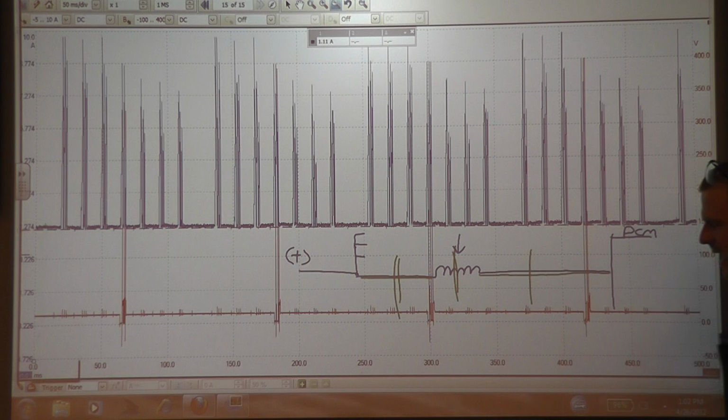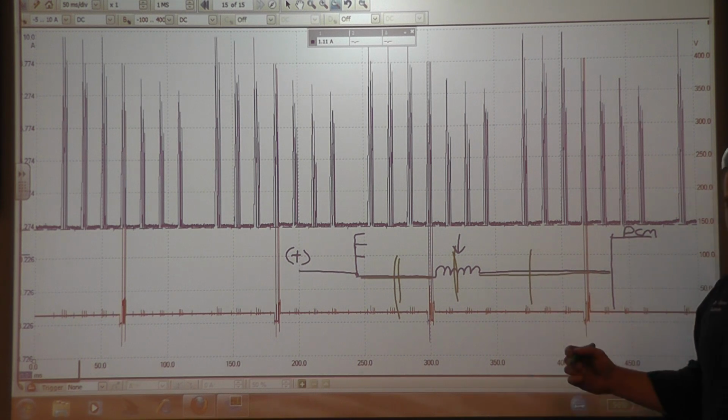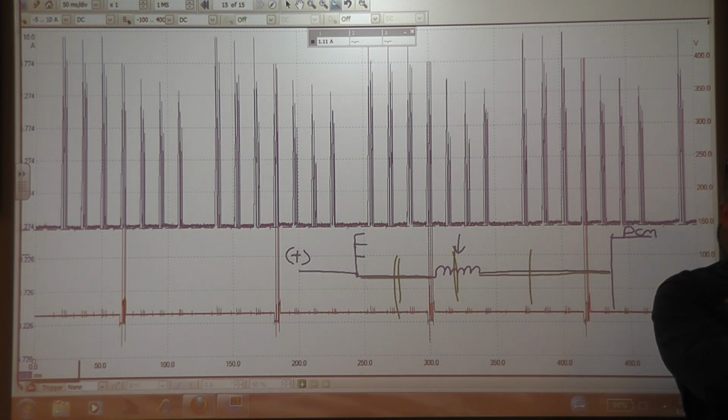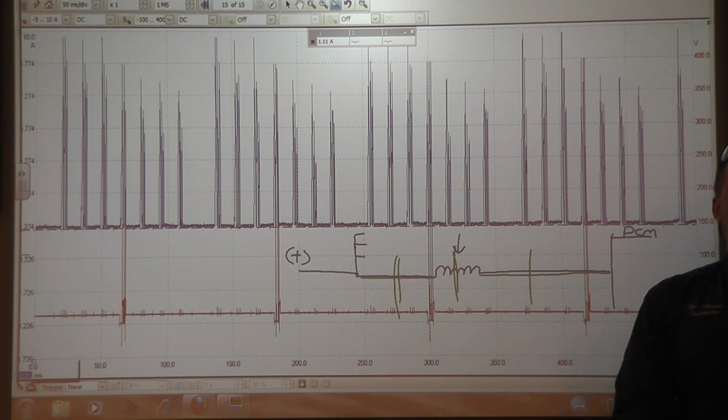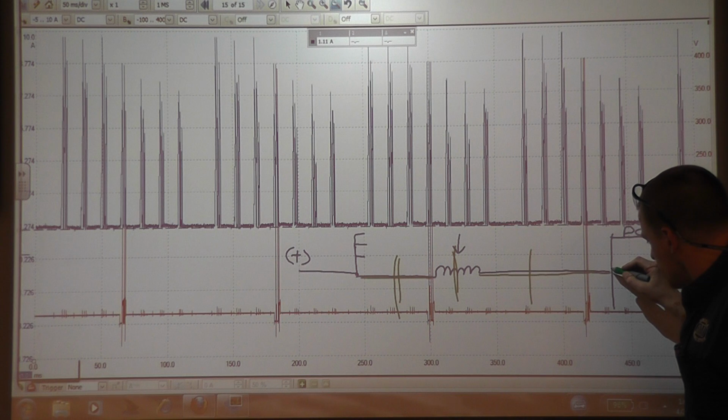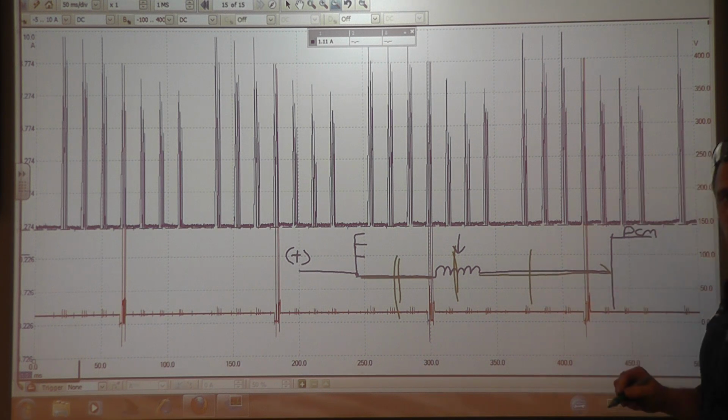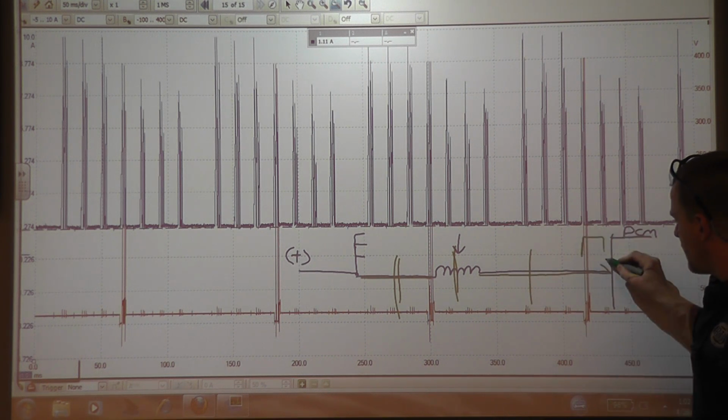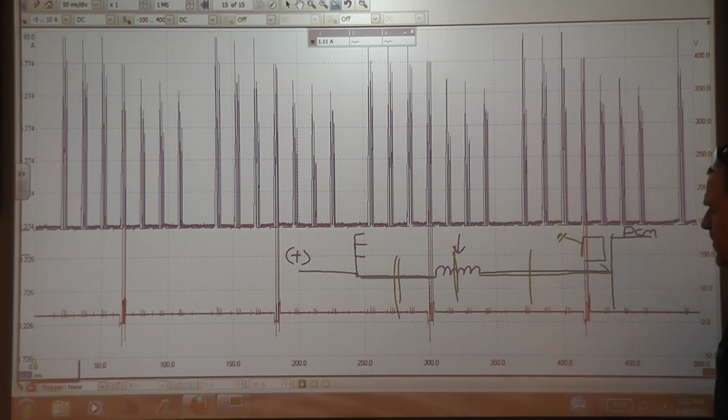So open circuit tests, what we're going to do, this is the next easiest one. The computer's already open, somebody's been here and already rewired some of the control wires on this car. So we're going to back probe the PCM on that control wire, and we're going to do a voltage waveform at the computer.